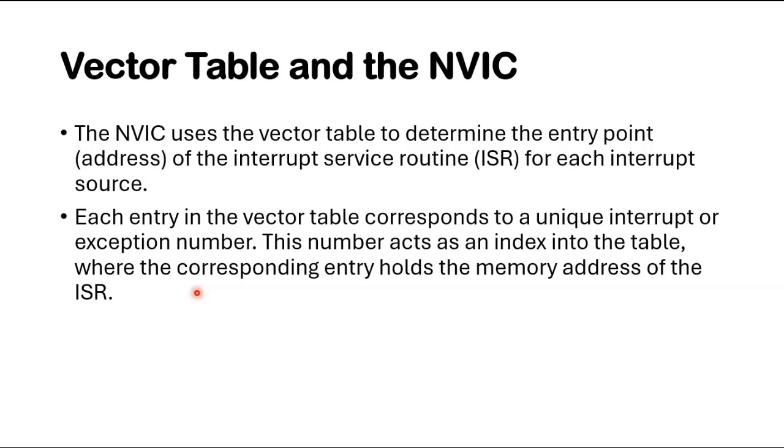Now, each entry in the vector table corresponds to a unique interrupt or exception number. Now, this interrupt number or exception number acts as an index to the table, where the corresponding entry holds the memory address of the ISR, or interrupt service routine.